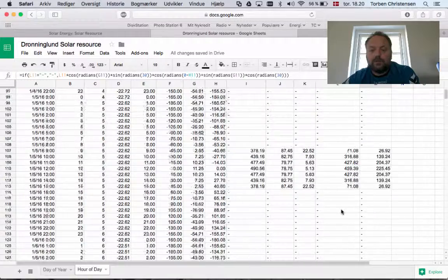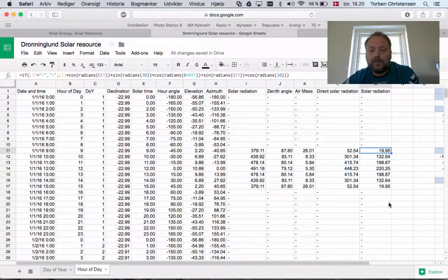And I've got numbers for every hour through the year. 1 hour we've got a medium power in watts times 1 hour, meaning I've got a number of watt hours in the formula here. And then I can just go on and summarize how many watt hours that's produced every month through a year, and the whole year in total. Hopefully that would get you a bit further on the assignment.